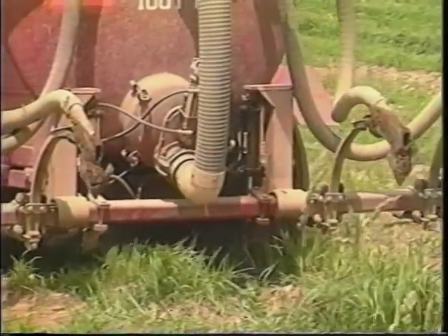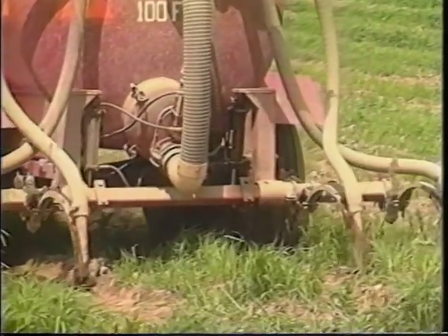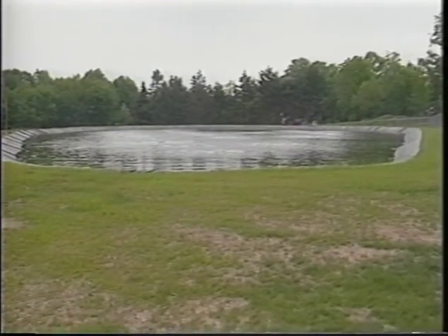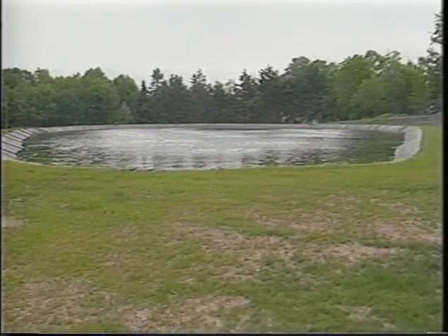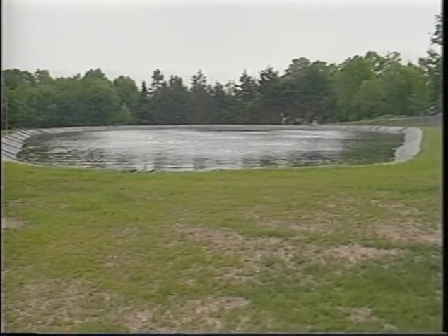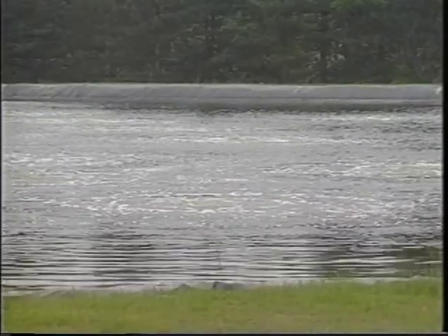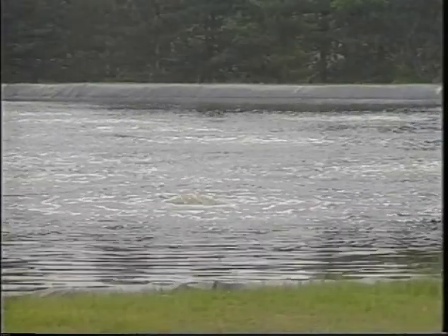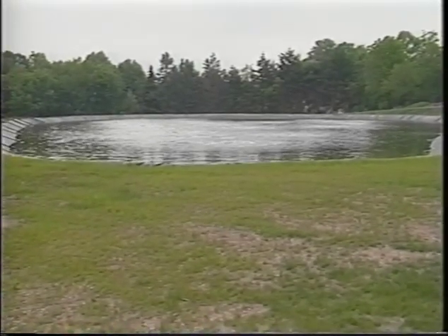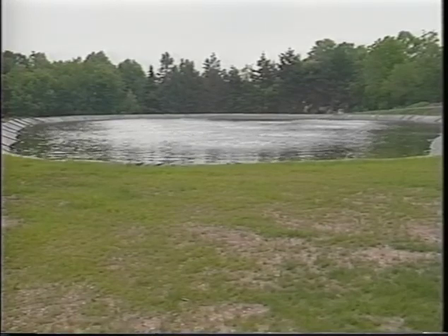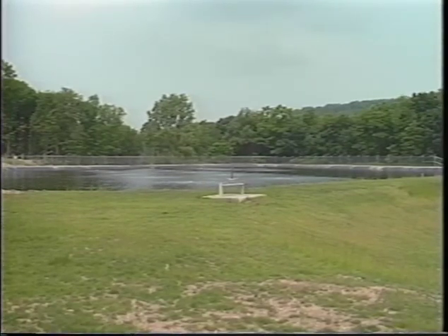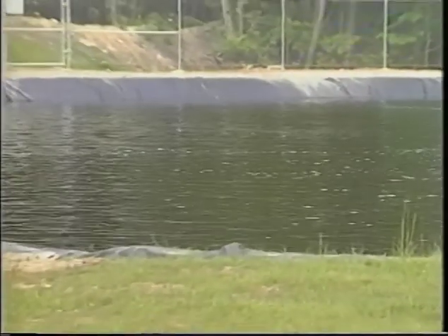All wastewater treatment facilities produce biosolids or sludges that must be disposed. This includes lagoon-type treatment facilities. While a lagoon may be able to operate for several years without removing solids, removal of solids will eventually be necessary. Budget monies need to be set aside for this purpose. When disposing of solids from a lagoon becomes necessary, it is a laborious and expensive process that requires advanced planning. It is not a matter of if, but when solids will need to be removed.